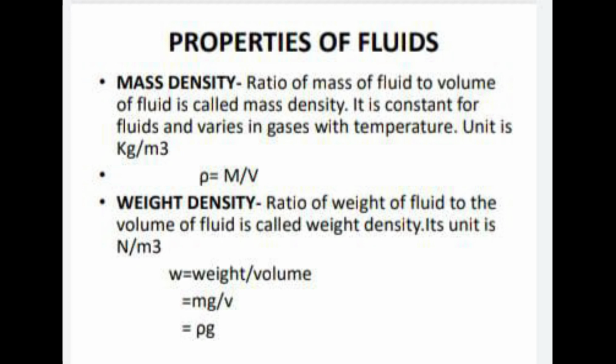The second property is weight density. As the name implies, the ratio of weight of a fluid to the volume of a fluid is known as weight density. Since weight is represented in Newton and volume in meter cube, its unit is Newton per meter cube.